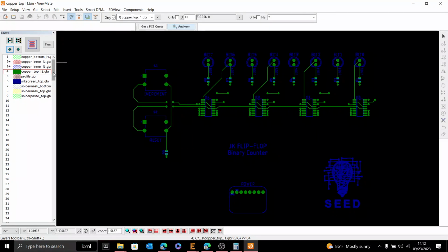Yeah, so one thing, I'm going to go ahead and point this out because this may be relevant to you one day. The very first PCB board, yes, we're going way back to a year ago, that I ordered through the company, we laid it out, it was looking all nice. When I get to it, there's a problem. My power and ground plane were shorted to each other. So we poured over the Gerbers, we poured over the schematics, we couldn't see anything wrong with it. We thought maybe there was some hairline, so we even tried putting 20 amps through it, hoping to blow that out if that was the case.